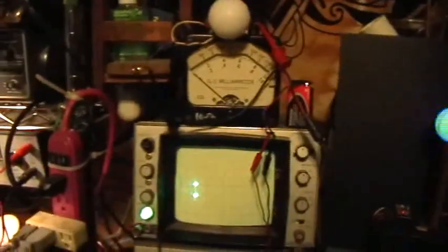What's this? It's a 9-volt battery, and its leads are just dangling right now. It's not hooked up to anything, but it will be in a moment. Okay, so now what I'm going to do is use the function generator's offset control to offset that signal down until the LED no longer lights.